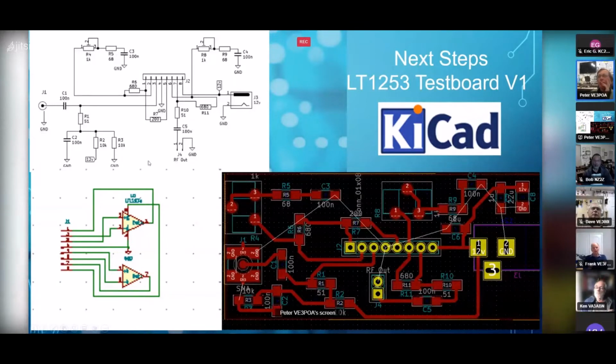And the other advantage too is the AD8008, which I do have on hand as well. It's pin for pin compatible, so I can plug that in if I decide to take a notion to do so, and see how that chip compares to the 1253. But I think the 1253 works well enough.